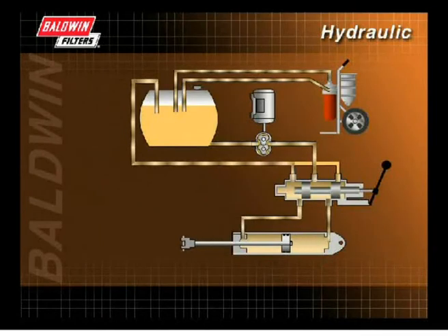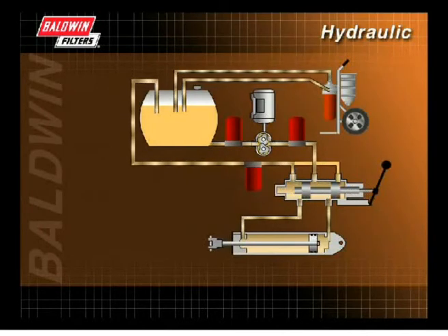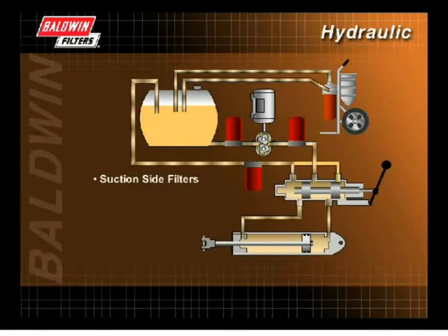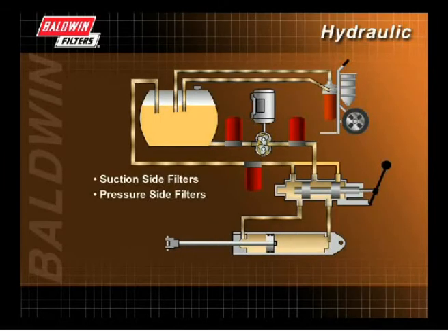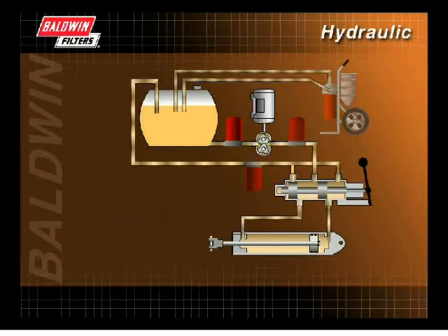Hydraulic systems are using an increasing number of filters. Increased sophistication and the use of sensitive, closed-tolerance components often require several filters in different locations in the system instead of just one. These filters include suction side filters, pressure side filters, return side filters, and offline filters.